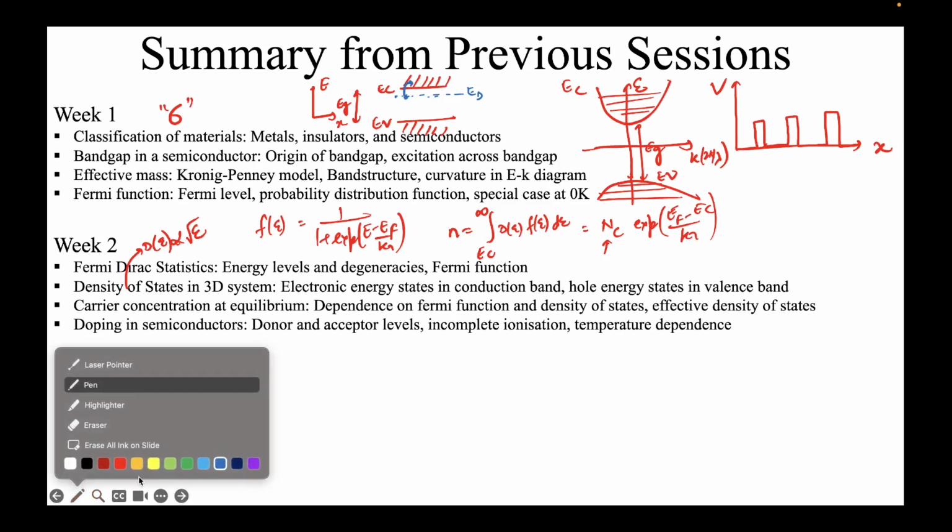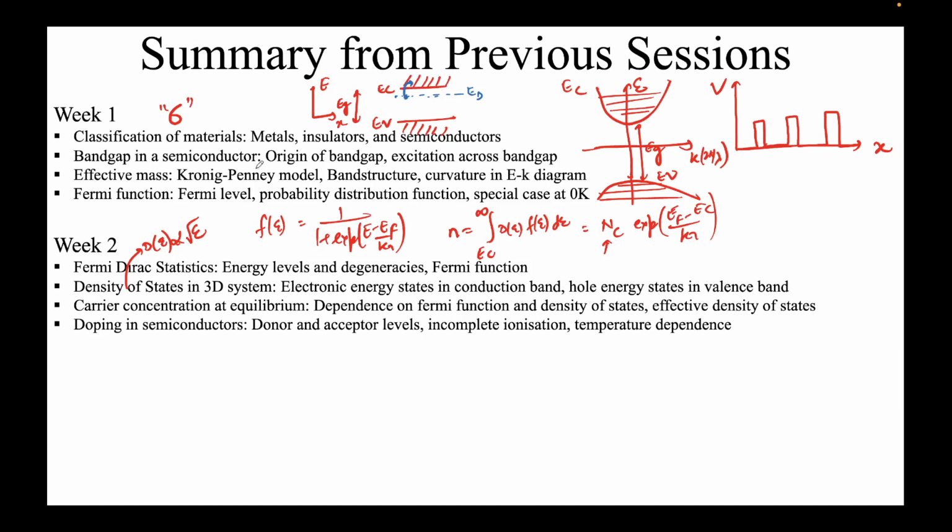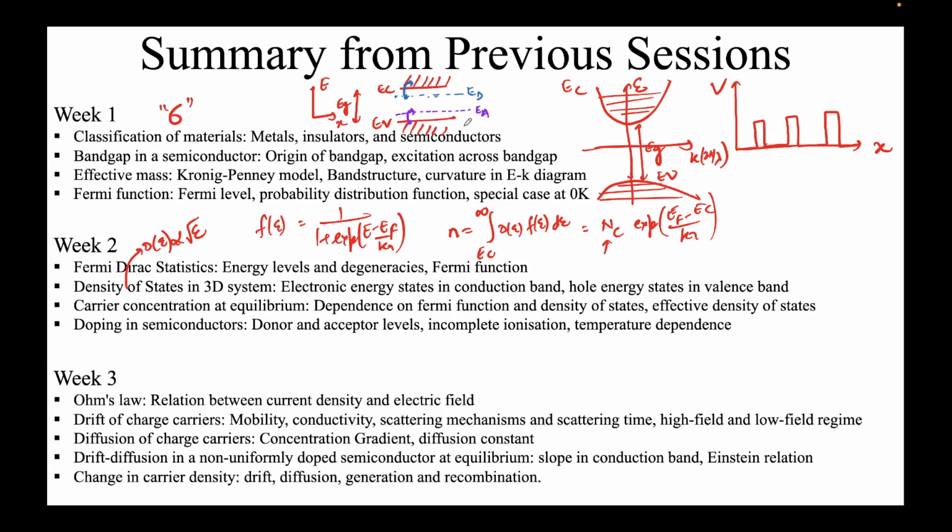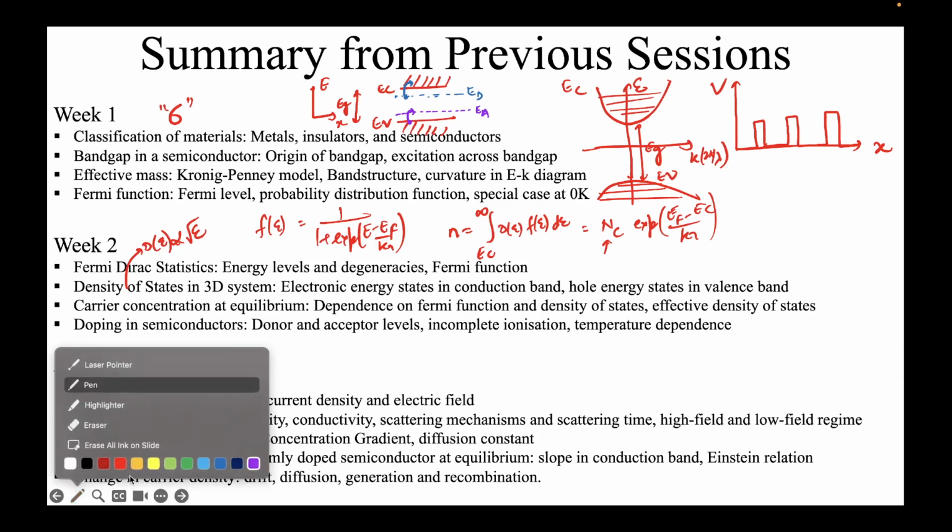On the other hand, there are other types of species which we call acceptors, whose level lies very close to the valence band, and electrons in the valence band can simply jump to this energy level. And these are energy levels that we have explicitly created by doping. Okay, and corresponding Fermi levels also change, but essentially now you can have electrons and holes available which can contribute to the current, right? And that's what we talk about here. How do they contribute to the current?